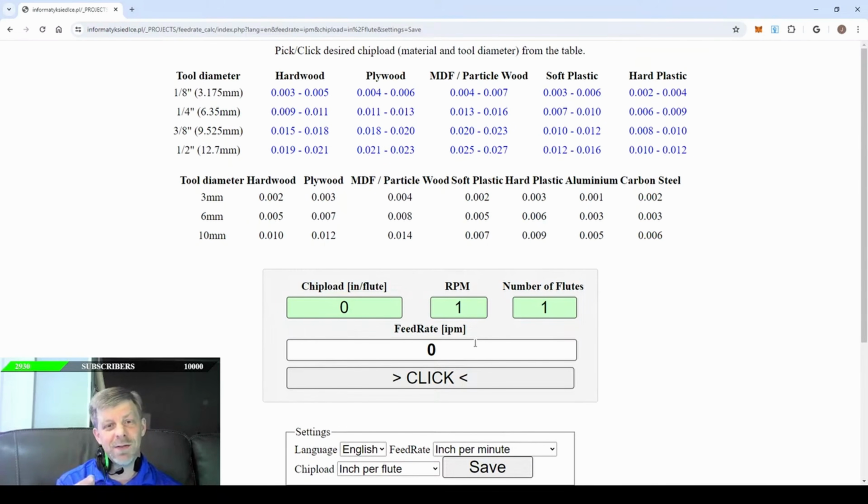Now, the other side of this is where the heat remains in the bit. The bit gets hot, and when the metal gets hot, it starts to temper. And when metal tempers, it becomes brittle, and that brittleness is what makes the sharp edge of the flutes become dull. So two compounding factors happen. Your wood has a lot of heat and warpage, and then your bit becomes dull. That dullness creates chip out, and your projects will not be as clean. So by having an optimal chip load, you will have a better cut in your projects. You will have less warpage, and your bits will last longer.